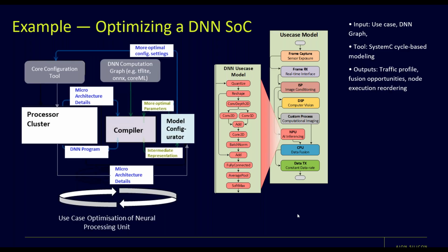Against that, we can actually add timing. Again, we have benchmark data that allows us to know what to expect from the processor when it's processing each of those particular functions, each of those particular operations. So we get a timing model for the task that's executing on that processor, and we know the form of the data that's being read and the data that needs to be written back. So this actually gives us something we can plug into the system model.